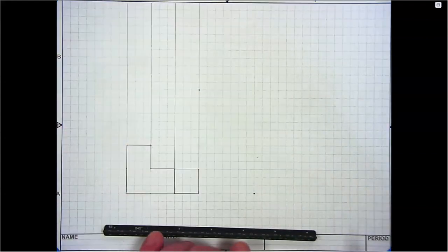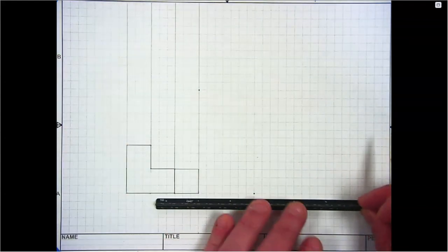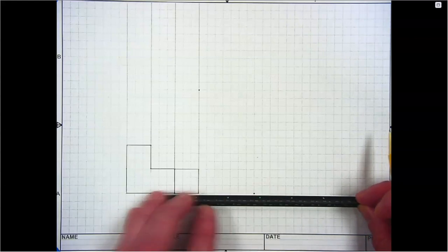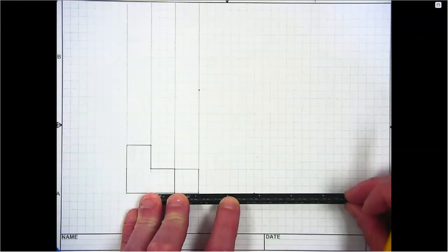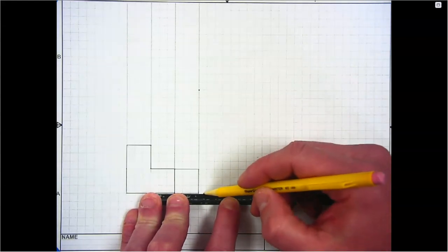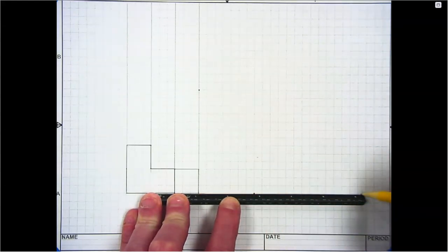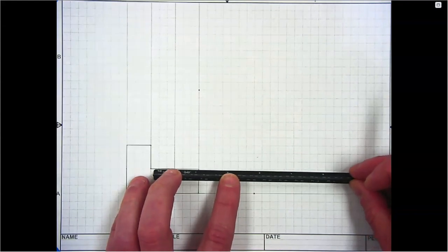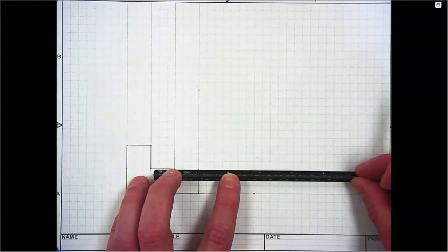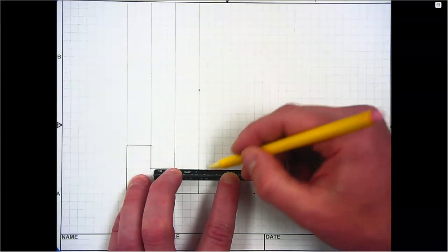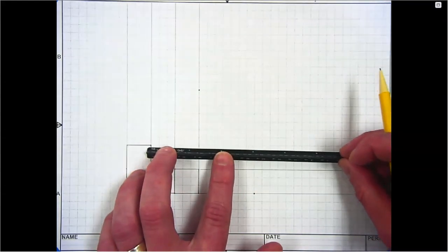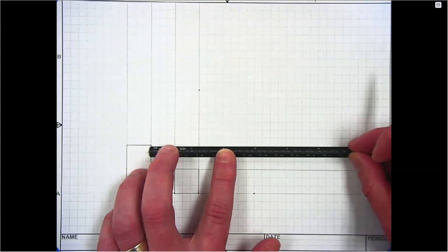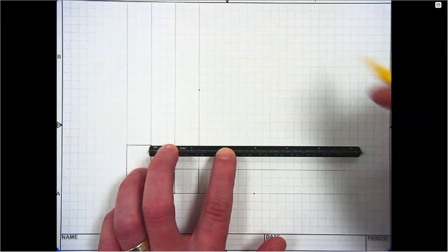We'll do the same thing for the height of the part, and so I'll start at the bottom of the part, and we're going to be projecting up where the part starts. So I'll project this line over. I'll go up to the next height that's represented in the part, project over another height line, and then lastly project over a construction line for the overall height of the part.